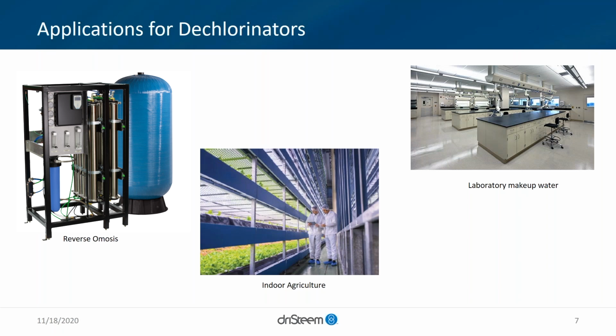Now, if we're talking ROs for humidification applications, the water quality that we're expecting to get at, let's say, a GTS LX is hypothetically 10 ppm of RO water, TDS. Over time, it'll go to 11, to 12, to 13 as that membrane breaks down. That can have a negative effect, in the sense that what you're trying to prevent with water treatment is going to happen, because you're sending poor water quality downstream.